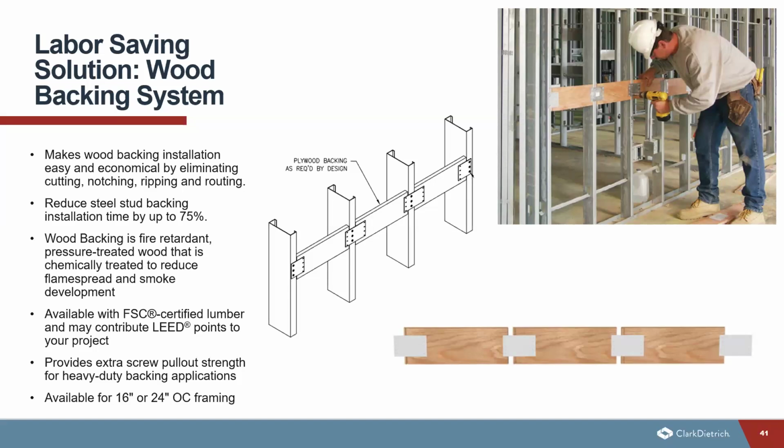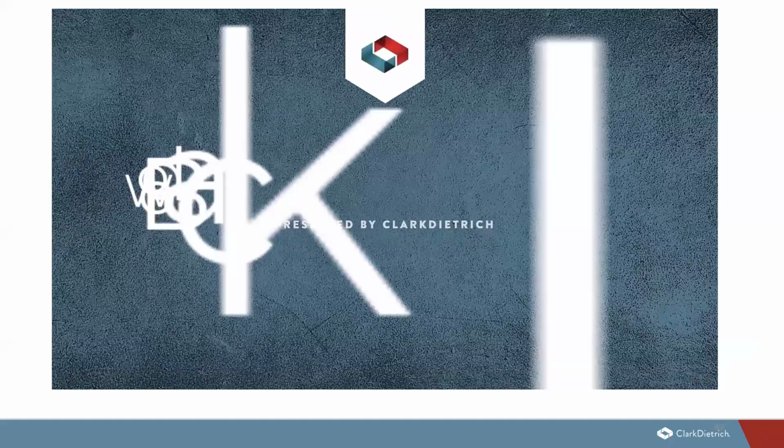So this piece that you see here on the slide, again, it has multiple pieces of wood. So there is a starter edge that you would use first to screw into the flange of the stud, and then it's going to wrap around each flange following that. So basically, once you screw in the starter edge, all you have to do is flex it around each following flange until your run is complete. So there is a video that also shows how this one is installed.